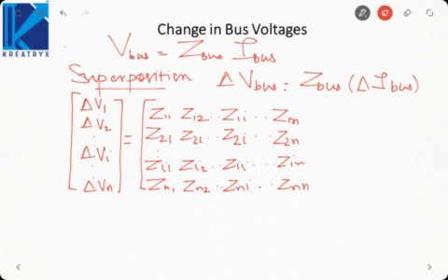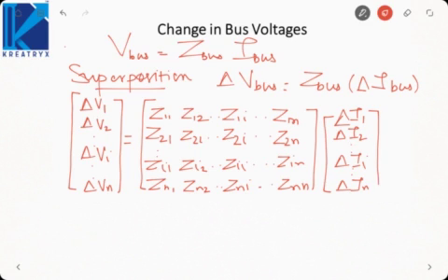This will be my Z bus. Here I have clearly shown the ith row separately. Now what happens is, earlier there was no current being drawn by any bus because we were assuming no load condition. But when the fault occurs, then the ith bus supplies a current of If.